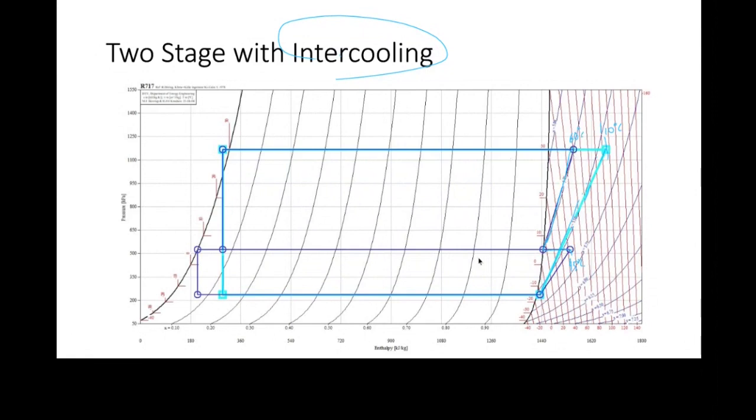So much cooler operation, better volumetric efficiency, and greater NRE because although I've got flash gas at an intermediate stage, I use the flash gas here for intercooling, and the remaining liquid enters into the evaporator, much less flash gas, let's say 8% flash gas, and so a much higher NRE than without intercooling. Difference being that much extra heat is absorbed per kilogram being circulated.